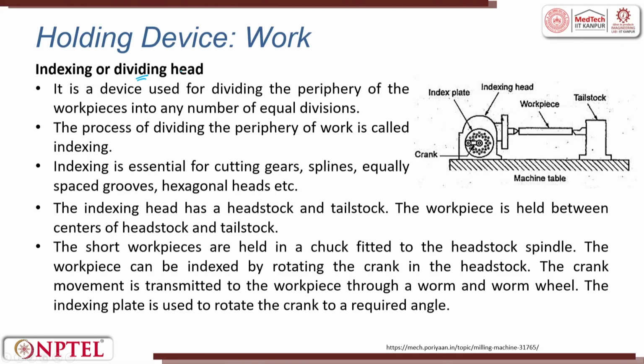When we look into the indexing or dividing head, where do we use it? We use this when we want to make a gear, or if you want to make slots. You will have an indexing mechanism. The function of the indexing mechanism is that the workpiece rotates to a fixed angle, and then you hold the workpiece. Now, you rotate, you stop, you rotate, you stop. When you rotate and stop, at that position you can do the operation.